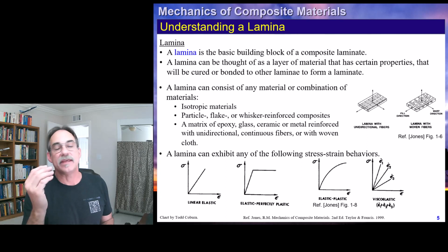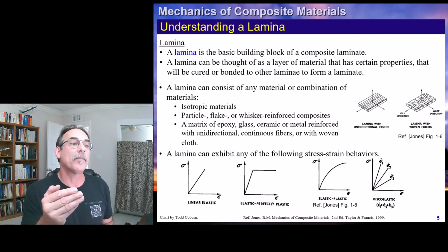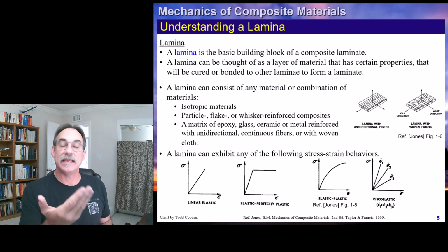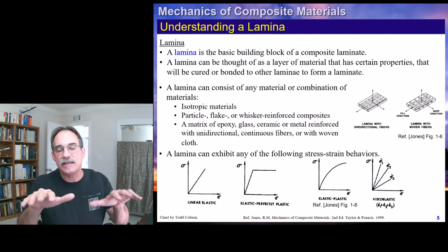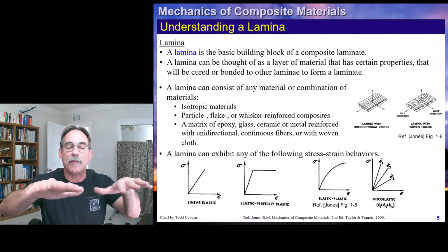And we've got the 3 mutually perpendicular material directions, the warp, the fill, and the transverse. We call them warp and weft, and that weft word could be fill. The reason we do that is when they're weaving these fabrics, they will often have them come off a machine that rolls that fabric out.